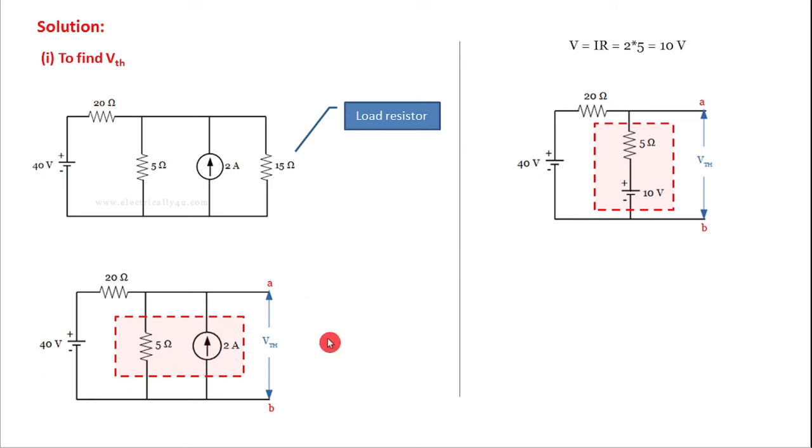Here this current source can be replaced with this voltage source, and the resistance which is in parallel with the current source can be drawn as the resistance in series with the voltage source. So now we have to find out the voltage across the 2 points A, B, which is nothing but the voltage across these 2 points. So let us assume the current I in the loop.